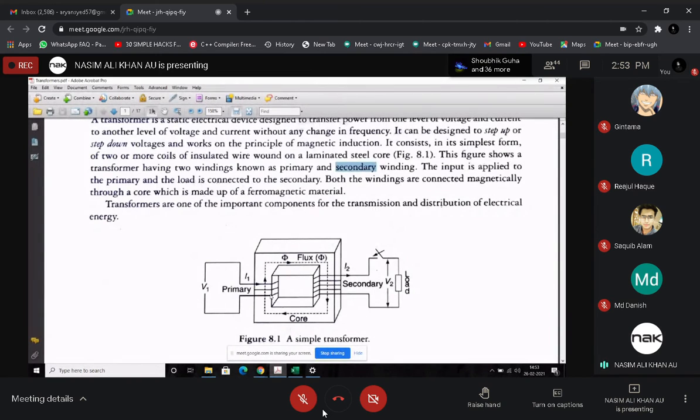यहाँ पर एक चीज देखो, यहाँ पर जो नंबर ऑफ वाइंडिंग्स है ये 1 2 3 है, यहाँ पर सेकेंडरी कॉइल है, this is number of turns is more. So what will happen, that current I1 and I2, automatically this voltage level and current level will differ, because that N1 and N2 value is different. When N1 and N2 value is same, there will be the same voltage or same current, but it is a step up transformer. When the primary voltage I'm giving is 20, might be I'm getting the voltage as 70, 80 or 90 volt. So how the transformer will work, now I'm going to tell.